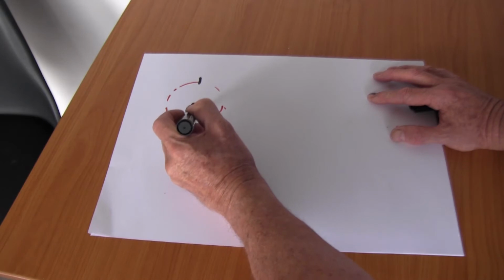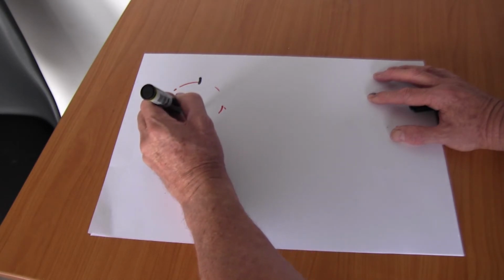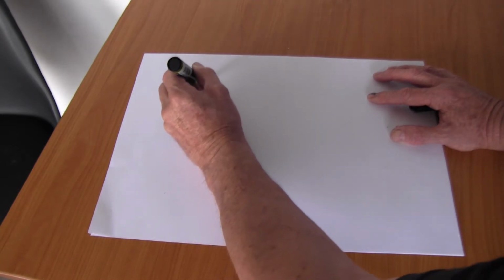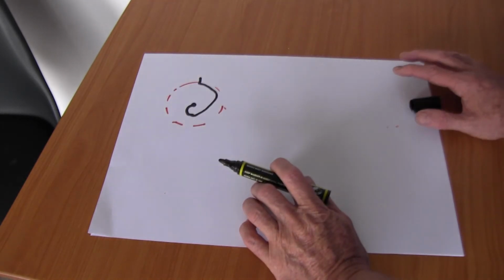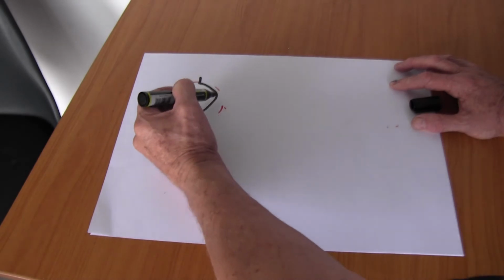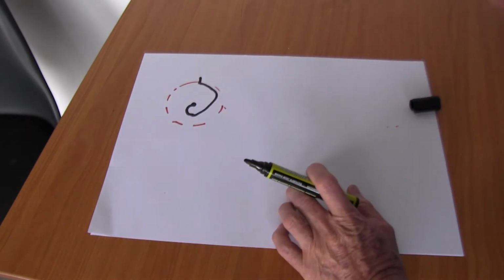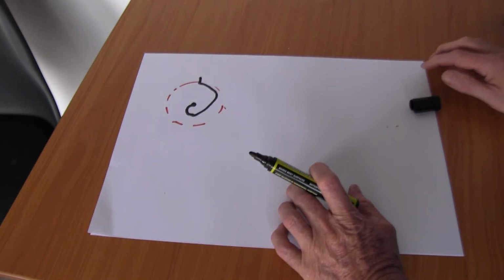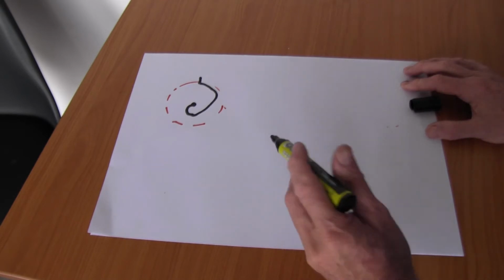So then we want to start our lead in from here, and we're going to lead in to a specific point, and then we're going to do an arc, which I'm not very good at drawing, all the way around here as the lead in to the beginning of the hole. Now this gives us a nice tangential entry point that maximises cut quantity.